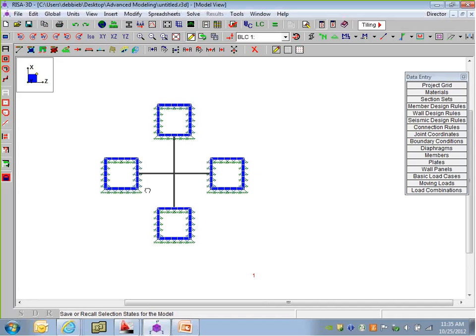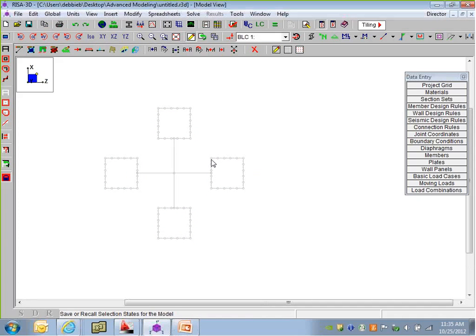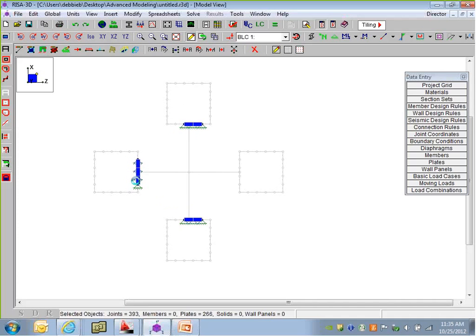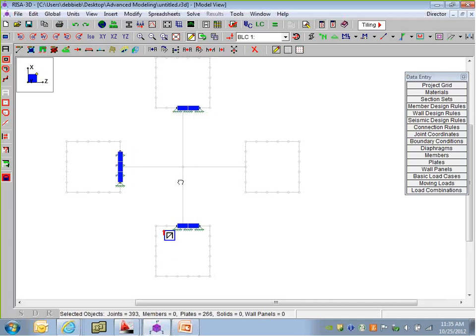So we could do things like select. These towers probably aren't just boxes, okay? We need access into there. These are just 10-inch thick concrete walls. They're not going to be empty, dead space typically. So what we can do is maybe delete just a portion of those out. You still see my center beams, and I'll just leave those for just a little longer. Those can probably be taken out eventually here, but we'll just sort of remove some of this area in here.